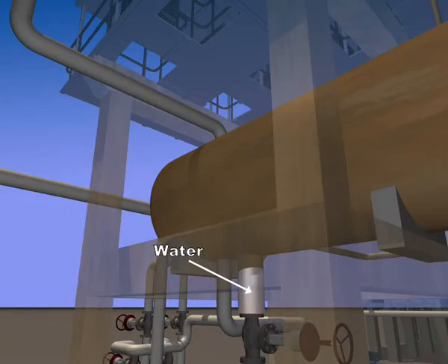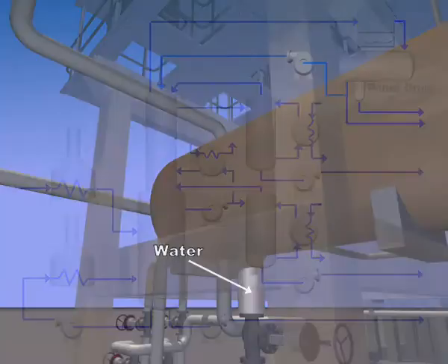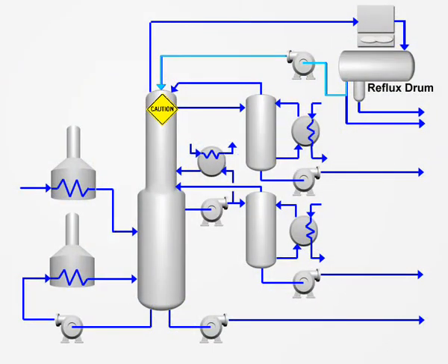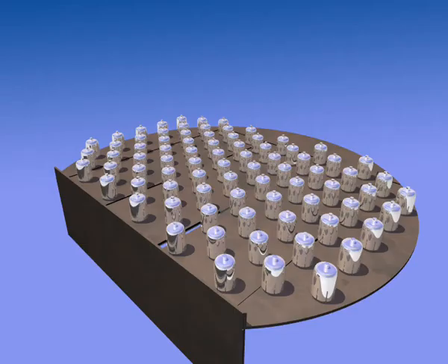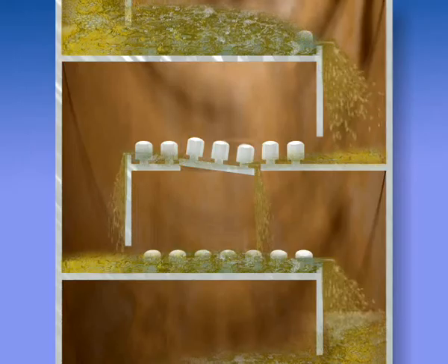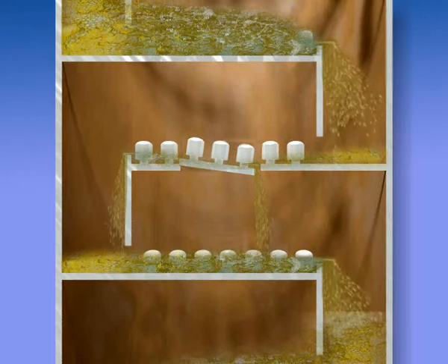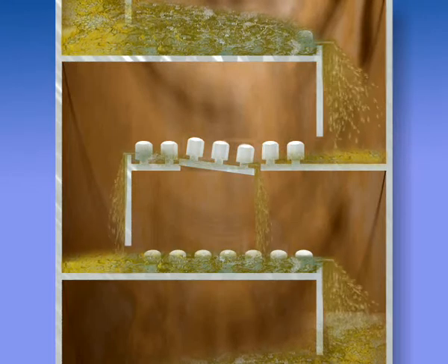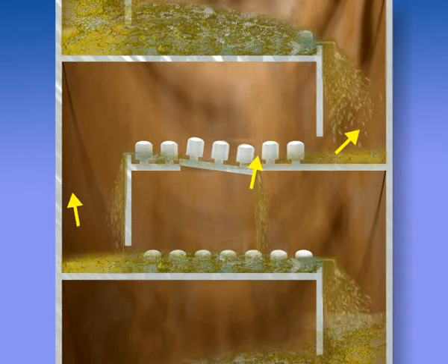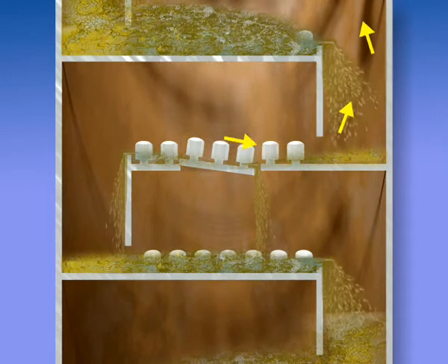We talked about the importance of purging water from the reflux and dry steam before introducing it to the column. Failing to do so will create a large pressure increase when the cold water and hot oil make contact. The trays can get damaged at their weakest points, the points where the different pieces are bolted together. The pieces can separate and lift out of position. As illustrated here, the liquid level is lost and the vapors are allowed to escape without making contact with the liquid.